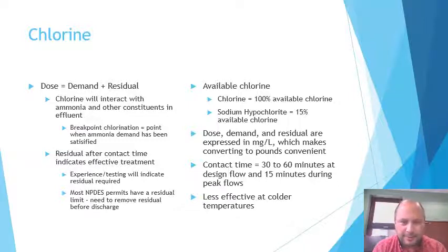I don't really remember exactly, but a lot of times you're going to have to add sodium bisulfite or some sort of sulfur dioxide or some other chemical to neutralize the chlorine and remove that chlorine residual before you're allowed to discharge. Some plants, I know that Cincinnati, one of their bigger plants, does not have a chlorine residual limit, but I think they're discharging directly to the bottom of the Ohio River, so I assume that that chlorine residual gets used up right away.